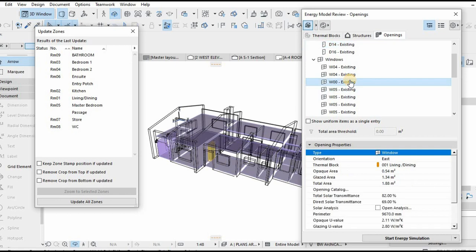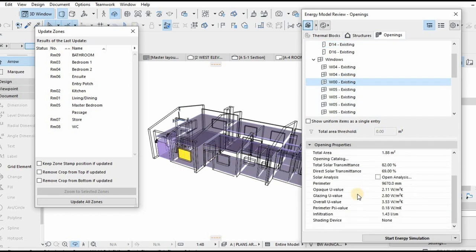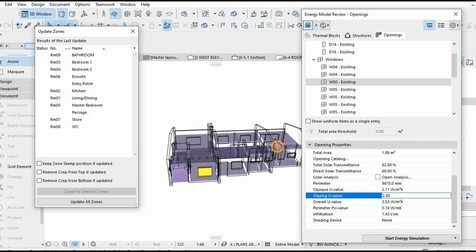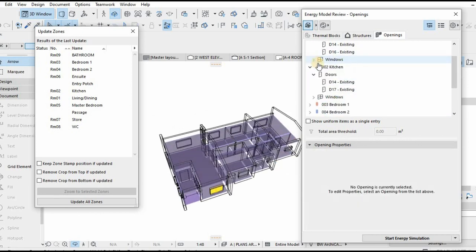Having windows, you can, if the window is strong in terms of penetration or infiltration, you could add, let's say these are aluminum windows, you can come and punch in specific data from manufacturers of the windows, the occupancy, U value, glazing U value, first things. If they give you information like that, that's how you could have an accurate energy simulation with accurate proper information from consultants. All right.